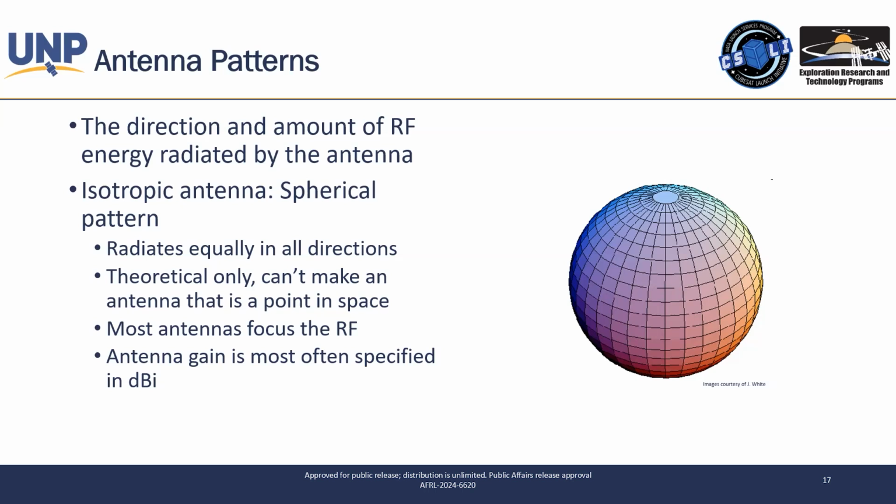So what Nathan just explained was that when you transmit light, there's some certain energy density in that light, right? It's a concentration of photons specifically. And as it travels outward, those photons become more spread out. When you see a light that's, say, 10 kilometers away versus 10 meters away, it's a lot less bright because a lot less of that intensity, that power, is incident on your eyeballs. Literally, antennas and RF waves work the exact same way.